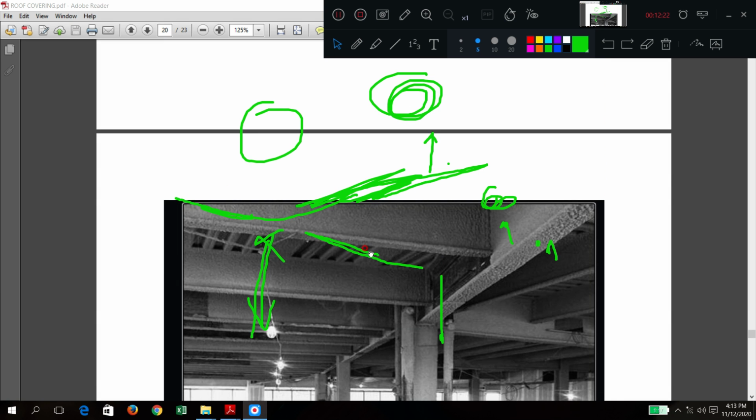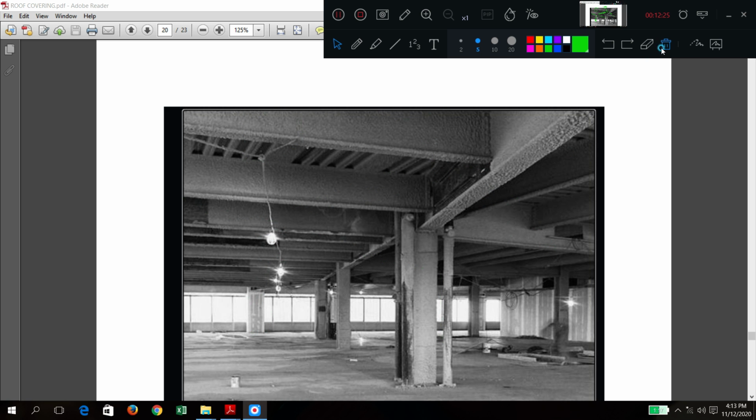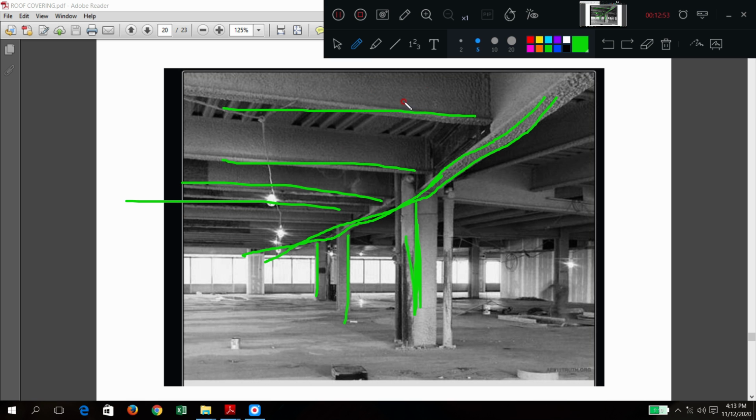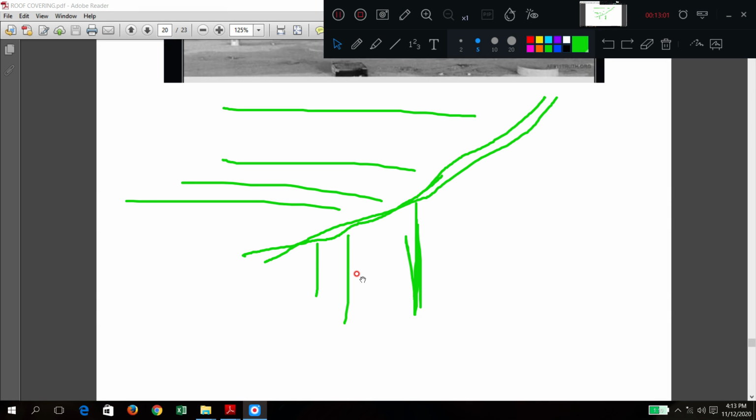You have beams here. Can you see in this diagram? More clarity is there. So you have columns. Columns are supporting beam. This is a main beam running directly over the columns. Wherever columns are there, this beam is continuously running. And this is called secondary beam. Just to understand, secondary beam. Above this the slab is going to come. This is used when the hall is very large.